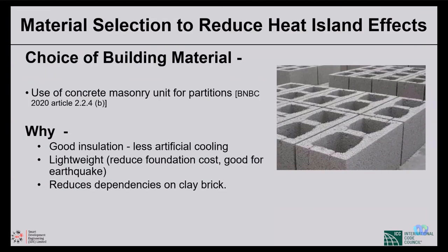Material selection to reduce the heat island. Choice of material, use of concrete masonry unit for partitions. BNBC 2020 Article 2.2.4b. You will find the necessary standards for that material. And why? We have a good insulation, less artificial cooling, hence we can do something about the heat island